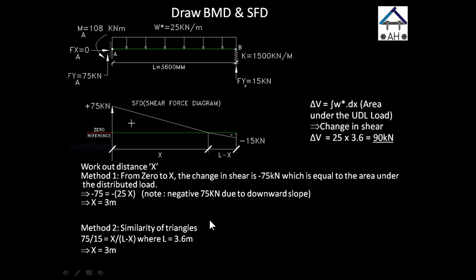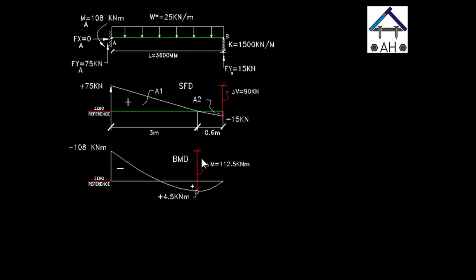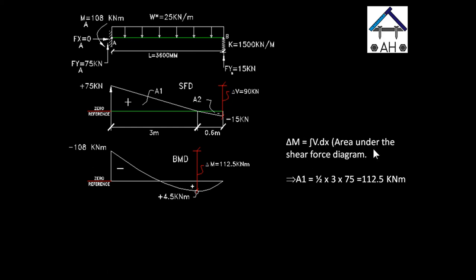Okay, so now let us go ahead and draw the bending moment diagram. We basically do the same thing as before. The change in moment is the area under the shear force diagram, which is the integration of V dx.